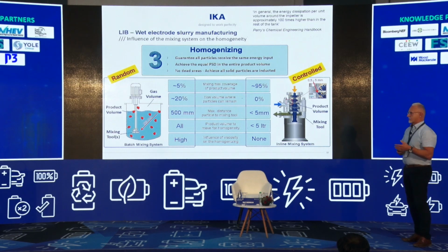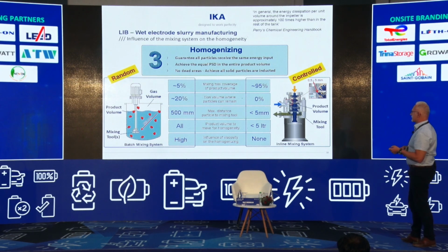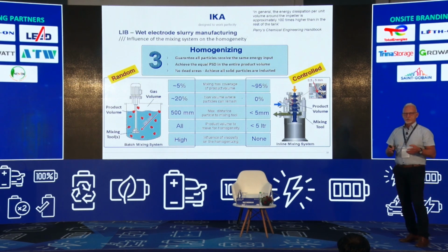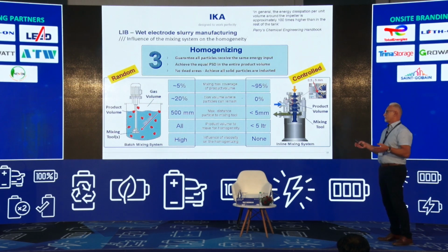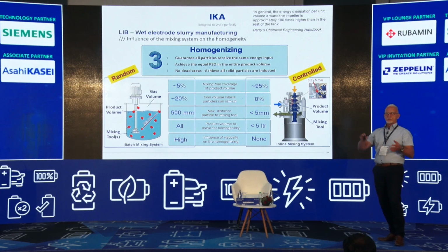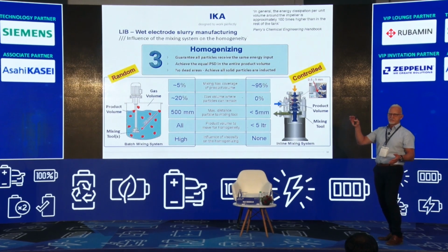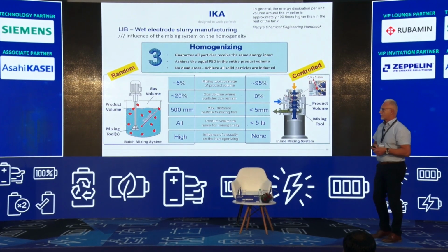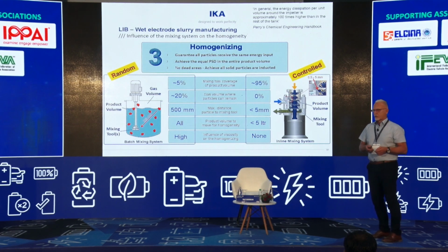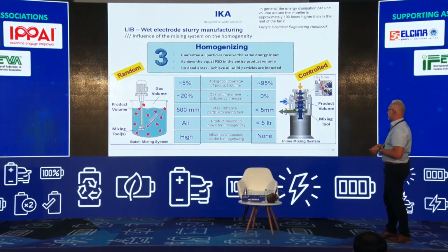Another thing is the dead room in such mixing systems, where some material can get stuck. And last but not least, it's a matter of machine size. How good is the mixing result? You are limited by the machine size. Otherwise, the time will be so long to achieve good quality that it's no longer reasonable to do it like that.